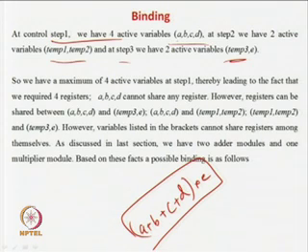So, we have 4 elements A, B, C, D, and we have to give some registers where they can be stored. Now, you can see in time step 1 A, B, C, D, all of them are active. So here you cannot save anything. In time step 1 you cannot share any hardware, because for A plus B plus C plus D, all of A, B, C, D are alive at time step 1.